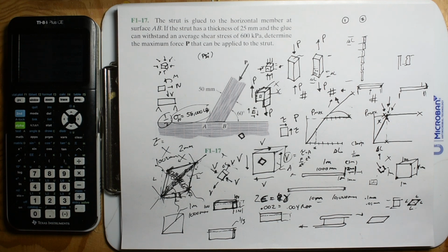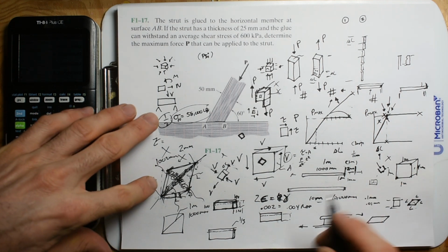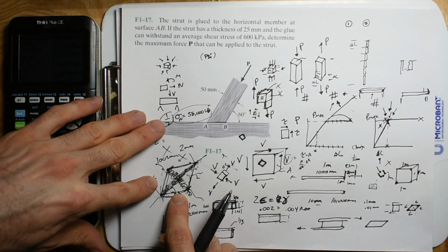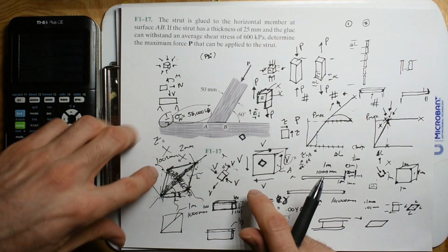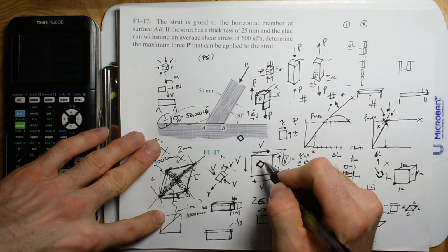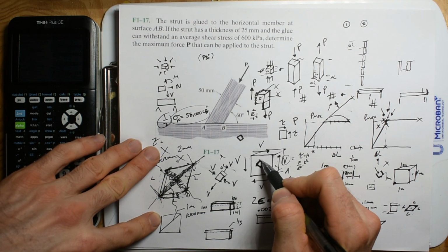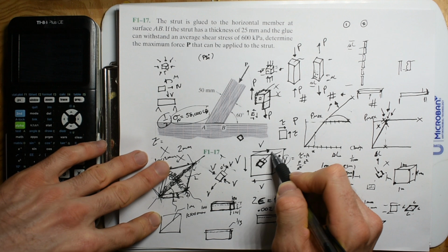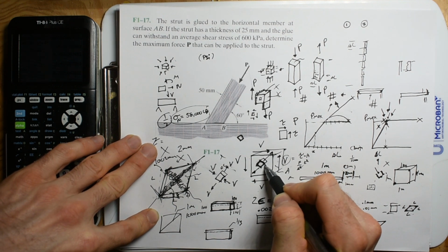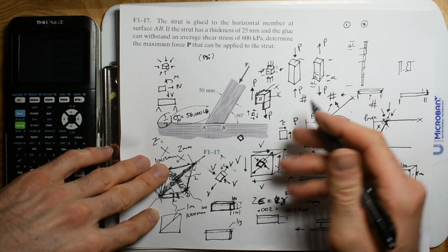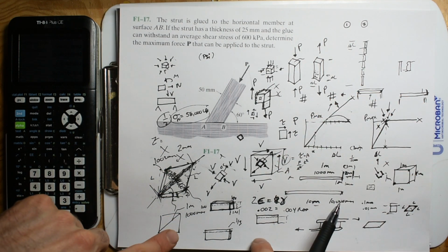Alright, so I'm just going to leave it there. But yeah, it's just fascinating that this is a fundamental in material mechanics: when you shear something, a 45-degree element will lengthen and compress, based on what we just did.